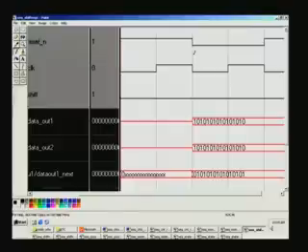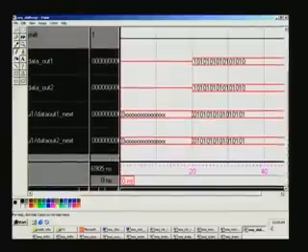Whereas in synchronous it will take effect only when the clock arrives. So, this is asynchronous for the reasons we have already covered earlier, and we see that data out 1 is preset by this value whenever reset is encountered. That is why you have the same 1010 appearing here, and so also data out 2, which is an alternative approach for the shift, and once again a corresponding next will be there, pre-shifting here.